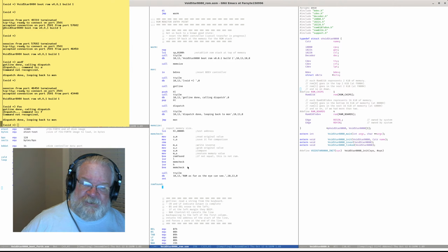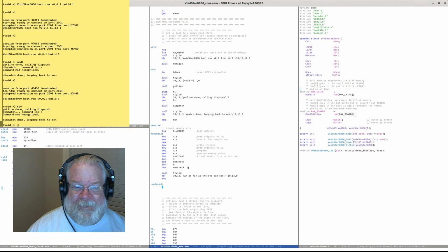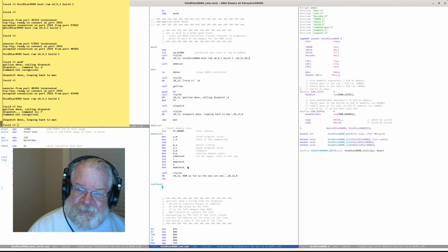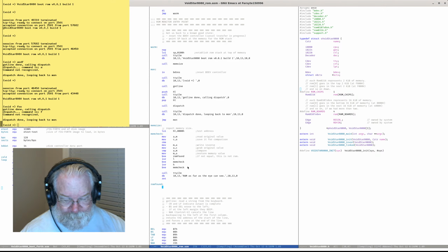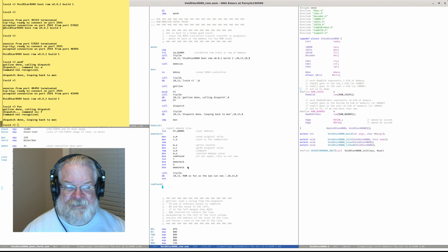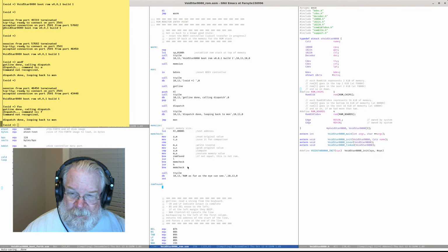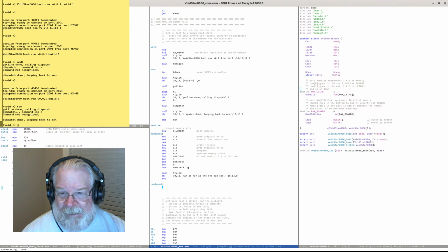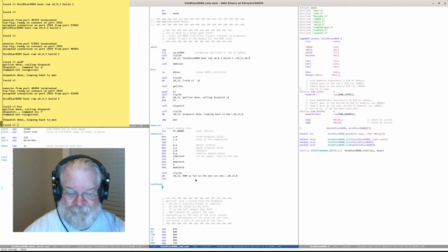In a real system, there is the possibility that I would write a byte that would go nowhere. It would turn around and read a byte from nowhere, and the data that I wrote would still be on the bus. On the simulated system, I don't believe I have that problem because on 8080 at least, between the two, you've got a sync pulse. So if that gets driven out onto the data bus, that's going to change the contents. So ROM found.